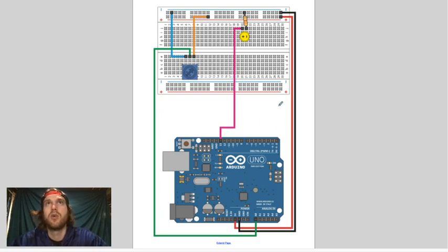Just like I said, we're charging up the power rails. You have 5 volts that's constant, that cannot be controlled by a port. It's coming onto the positive rail, which is what we did last time. And you have a ground going to the negative rail. So anything that we connect from anywhere else, as long as it gets back to ground, we're good. So we just got to connect it to that negative rail. Okay, and it doesn't matter whether it's on or off. So from here, follow the positive and negative. We have electricity goes up through the potentiometer, or the pot, and then back to ground, all the way back to here. Okay, so that's one leg of the circuit.